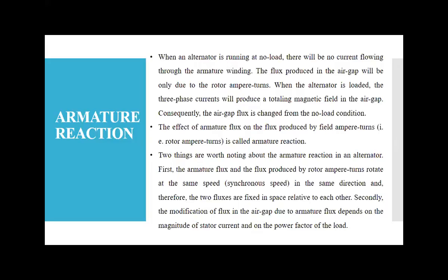Suppose you are connecting a purely resistive load. The alternator is not aware whether my power factor is unity, lagging, or leading. What does the load do? Your load draws the current from the alternator. So suppose your load is purely resistive in nature, then by default your alternator generates the unity power factor.